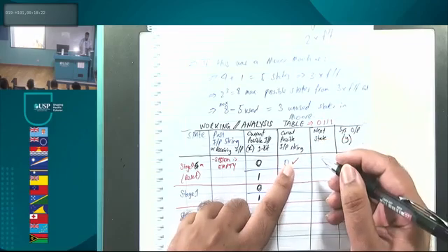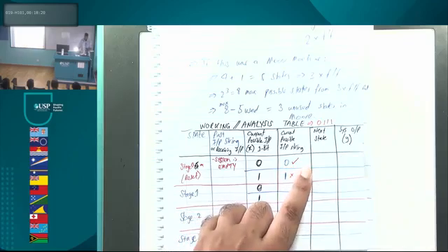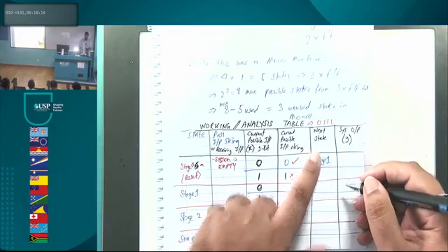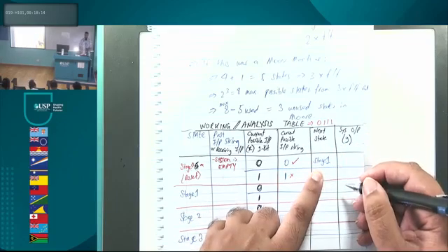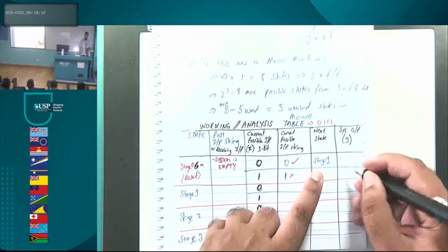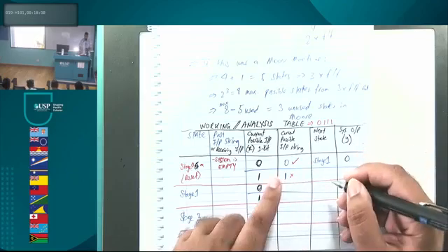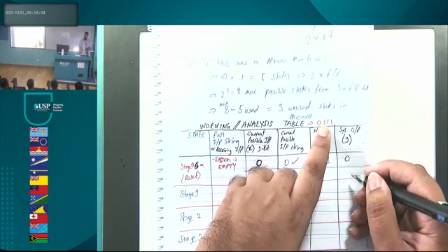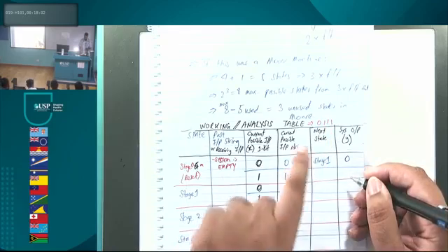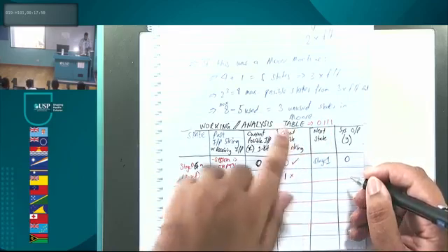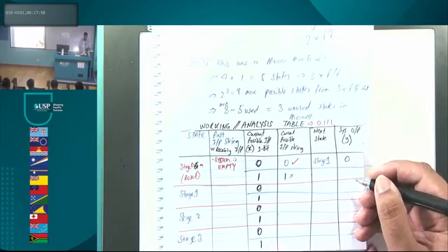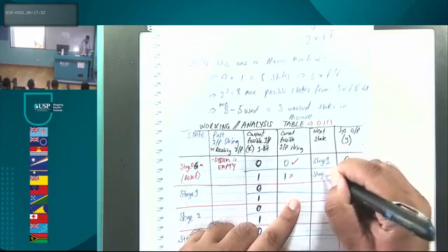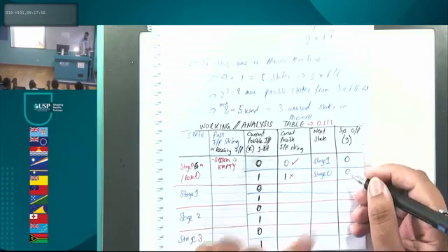Because this one qualifies, he goes to stage 1, the next stage. What is the output in this case? It still remains a 0. In fact, the output will always be 0 until we hit 0, 111 in this column, then we'll have a 1 out over here. Now 1, we're stuck. We can't progress, so we'll be stuck at stage 0.